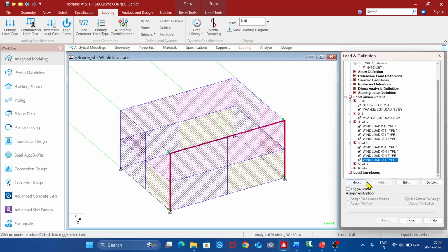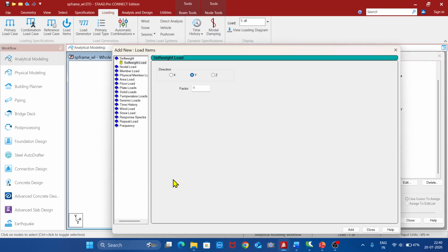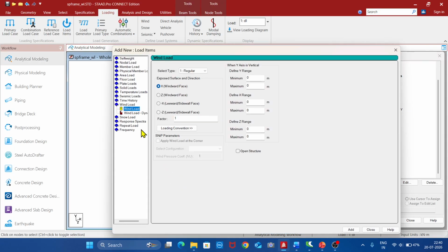Okay. Similarly, click plus z, click add, click wind load. So wind load, windward side plus 1, click add. Then in the leeward side, this is the leeward side also plus 1, add. And side wall for x, so side wall for x we should take this, so plus 1, add, and similarly minus 1, add.